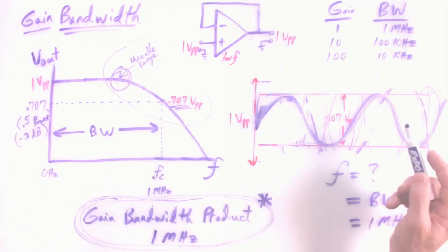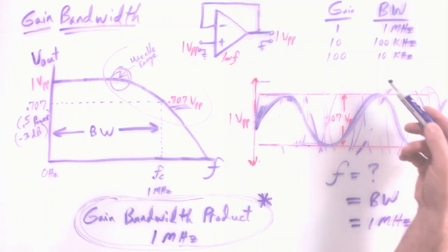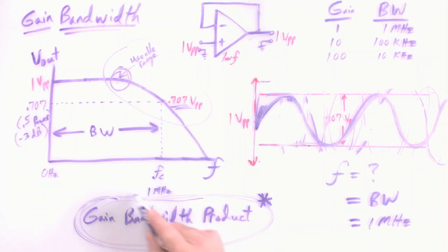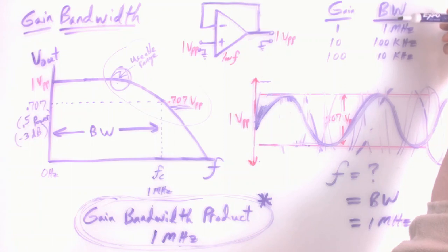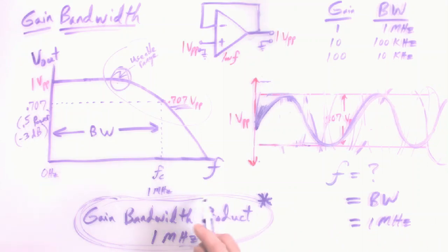As far as op amps, I kind of remember reading again somewhere, and we can experiment, see how our 358 stacks up, that the gain bandwidth product was not perfectly constant. It actually varied over an operating setup range as you varied gain, but it still gave a ballpark range. So yeah, I'm hedging a lot there, and I know, and that's fine. And we can experiment to see what our 358 does. Does the gain bandwidth product stay constant?